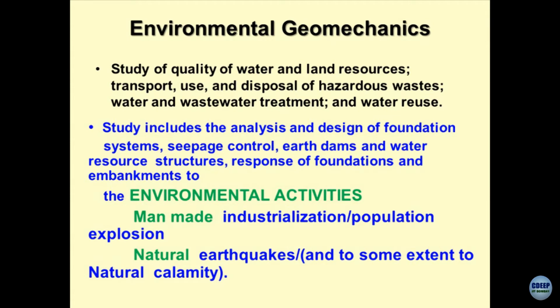Does anything else come to your mind apart from earthquakes? See, hurricanes and tsunamis play a very important role. I have been dealing with several examples in our own country where, post tsunami, the rehabilitation part, particularly in the Andaman and Nicobar area, became a very big challenge. To give you a quick example, a tsunami brings a lot of sediments along with it, and these sediments get deposited on the coastline, and now the infrastructure on these loose unconsolidated sediments is going to be a very big question mark.